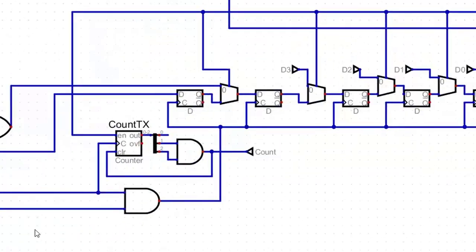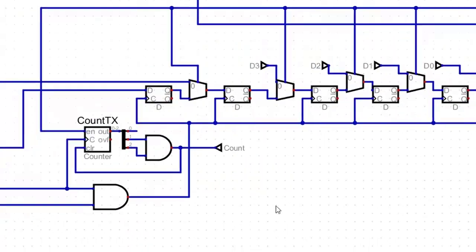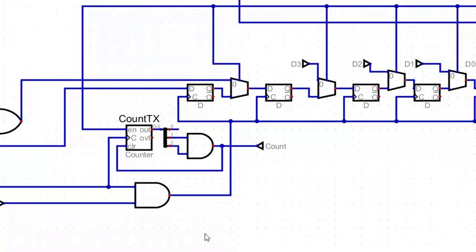I'm guessing it just needs a normal clock. Exactly. So what are you doing with the clock? You're hiding the clock while your state machine is in state 0. Do you see that? That AND gate is hiding. That's unnecessary then. Yes, exactly. You're hiding the clock from your flip-flops while you're in an idle state.